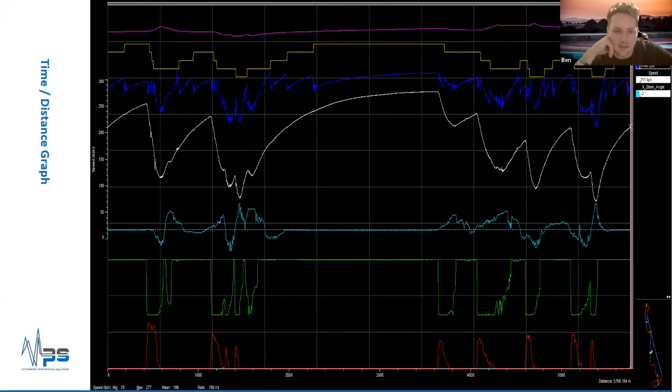The other thing I would also reiterate is that a lot of data analysis software, when you first load in a channel, say your speed channel, sets the limits of what you see on the y-axis here. So this is a good example. We've got the speed, and if the car ever did 0, when it stops, this white line would drop down to 0. So it sets the limits of this display area.